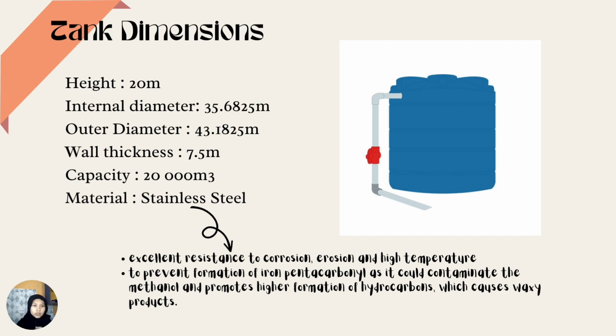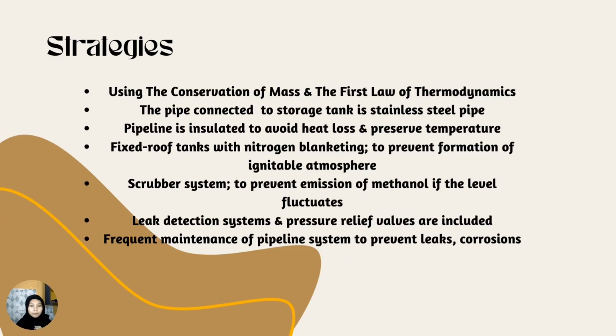The material that we have chosen is stainless steel. This is because stainless steel is excellent at resisting corrosion, erosion, and also high temperature. Using stainless steel also prevents the formation of iron pentacarbonyl, as it could contaminate the methanol and promote higher formation of hydrocarbons, which could cause waxy products.